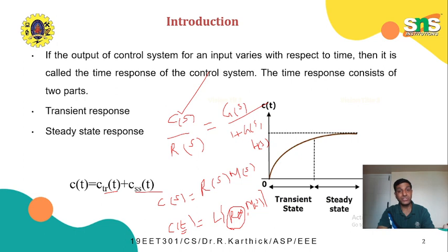It can resemble a sudden shock, it can be a sudden change, or it can be a velocity type input, which varies linearly. All these are characteristics of an input which occur for any system. But our problem is that these inputs may not be known ahead of their occurrence. So in order to model a control system, we generate signals which resemble these characteristics in the laboratories. These signals are called test signals, which are used to model a system.